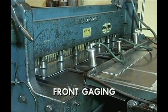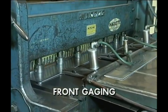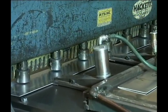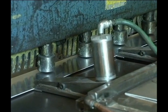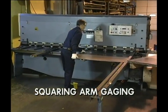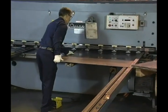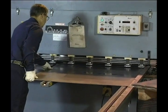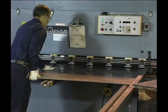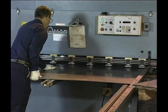In front gauging, the sheet is located with respect to the cutting edge by means of adjustable stops or gauges located in the table or front support arms. Squaring arm gauging, with the squaring arm mounted on the end of the shear, enables the operator to shear a 90-degree corner on the material. The squaring arm can be mounted on either end of the shear to distribute wear on the knives.